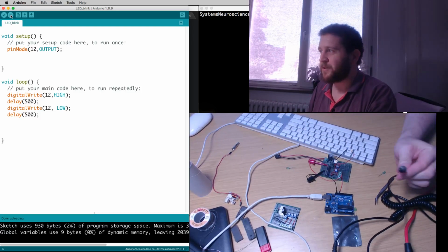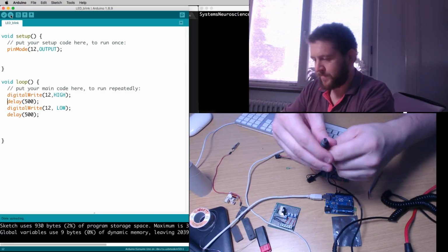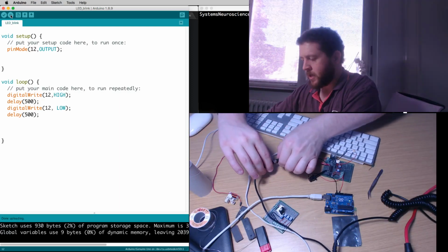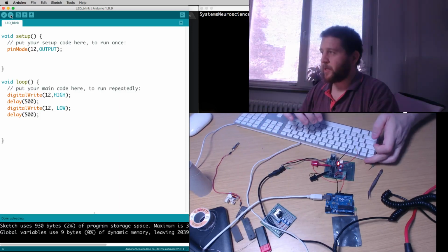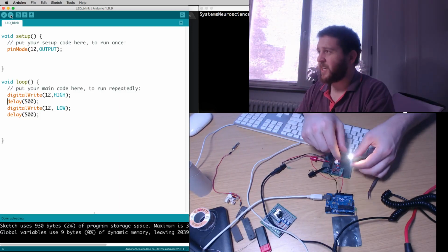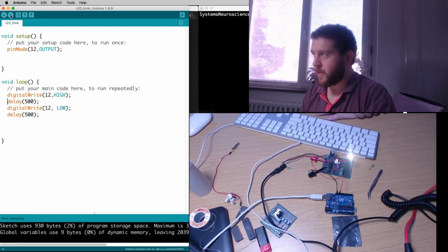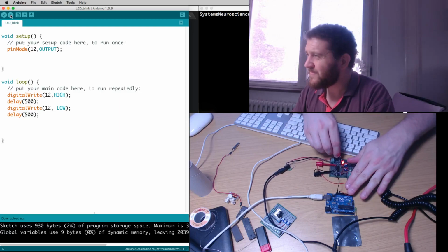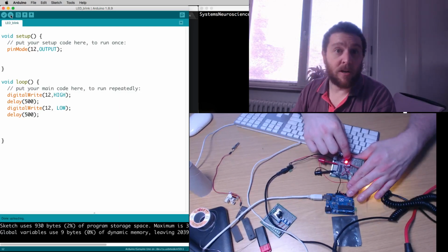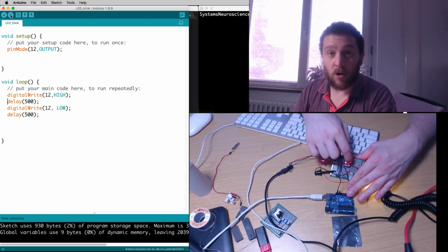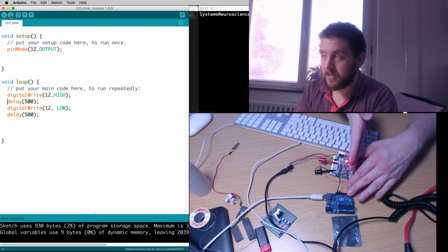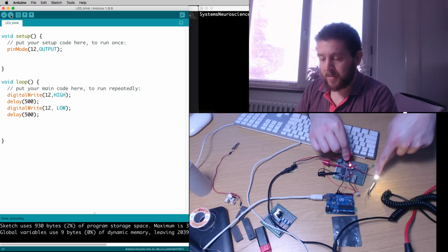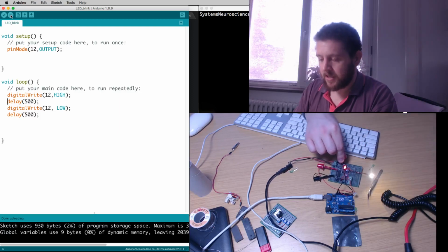Well, we now need to put in the 12 volts. So if I take this, this is just coming from a wall wart that's plugged into the wall. I turn that on. There we go. You can now see that bright LED light. You might also be able to see, if I move this down here, that our power LED is also lit up. So that means that I've got at least 9 volts running to this side of the circuit board. This side of the circuit board down here obviously is then going to power your LED lights.